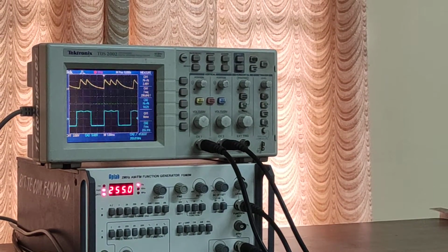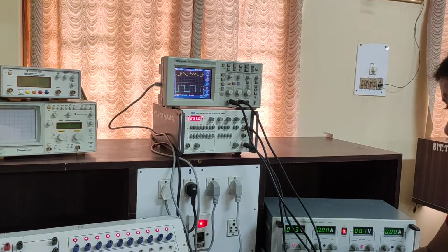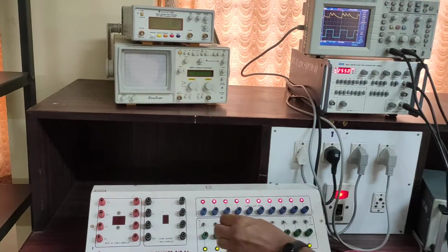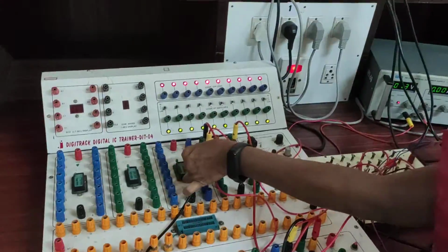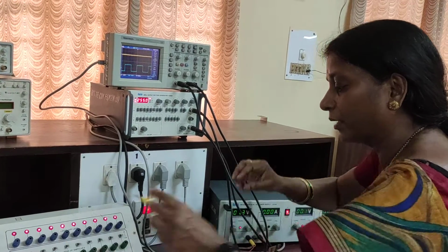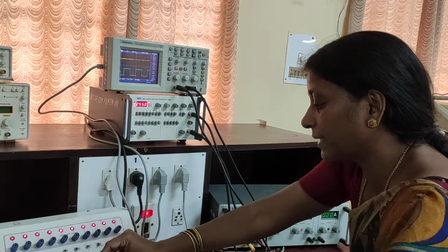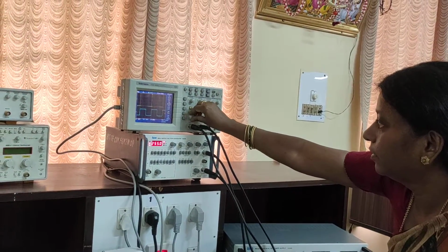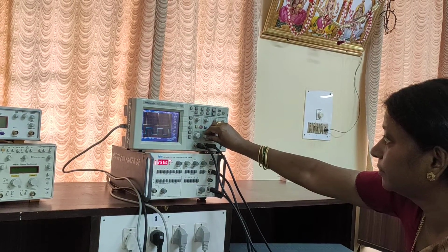So this signal is applied as a input to the comparator. Okay, so input to the comparator is pin number 3 here. Okay, same signal you will get here, pin number 3. Okay, this is the same signal you are getting at pin number 3 also, same charging discharging. So I will show you at pin number 6. Next. Pin number 6 is the output. Okay, so you are getting recovered message signal.